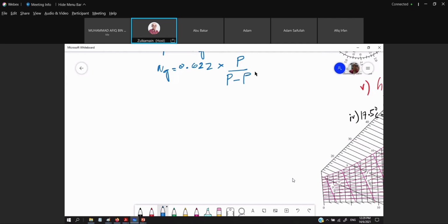And in this case, we are going to assume that the vapor is saturated. So this should be our PG. The PG we have defined just now, we got around 3.1698, and this will give us the value of omega G as 0.02009.